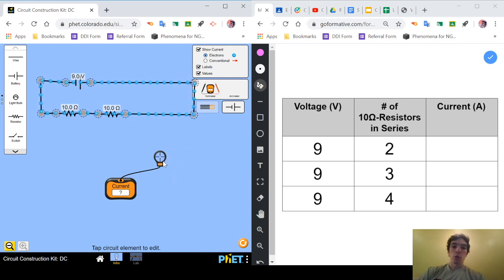And so you would measure the current to fill in this table right here, just the exact same way as you did before. I won't do that here because I'm not trying to give away any answers. But then you could cut this tie and put another resistor in there, and for that four resistor circuit, you could even put that there as well, and then measure the current and see how that current is affected for each number of resistors in this series circuit.